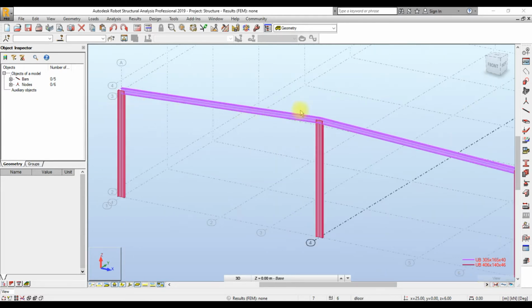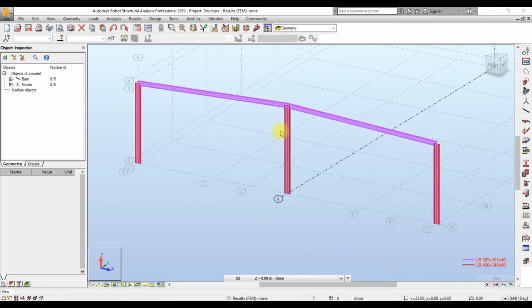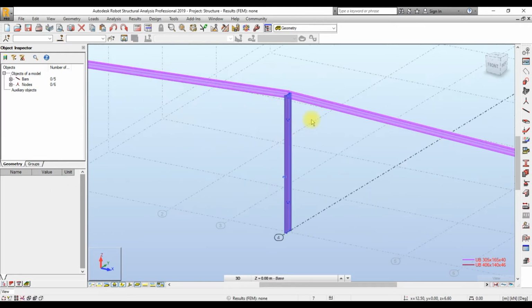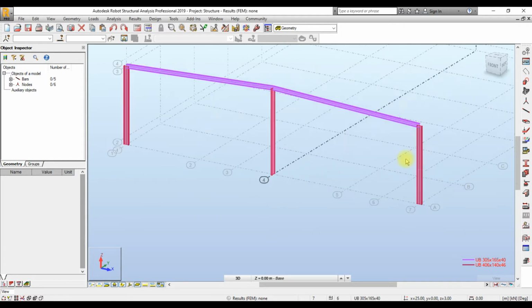So now for this I want to change it, I want to align it the other way. You click on it. After clicking, you come down here to your gamma angle, then you change it to 90. You can rotate, but you should be careful on how you rotate because it has a major and minor axis, whereby it will act differently on each part you rotate to.